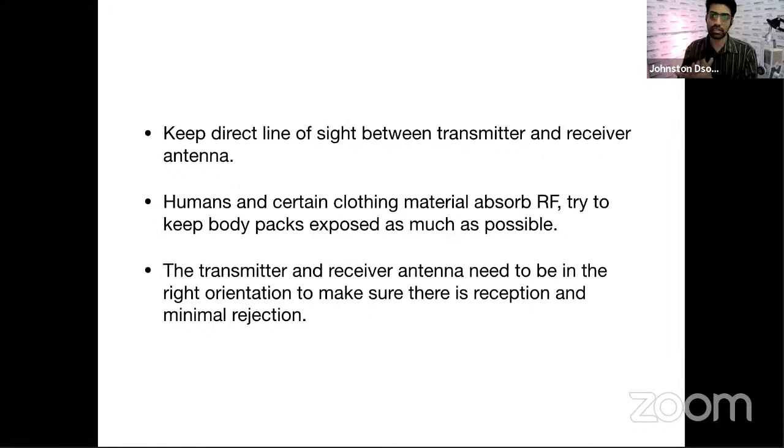Okay, so three things. Make sure line of sight is maintained. There is no obstruction between. Now these body packs are basically meant to be in very close proximity to the body. So try to make sure that if it's a transmitter, the transmitter is somewhat facing the receiver. I mean, it's not possible all the time, but you need to take care of it and keep an eye out for it.